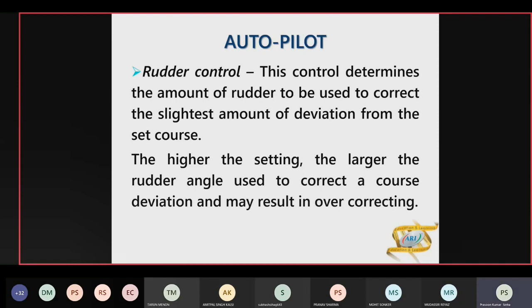To control the ship when she is going off heading, we were doing 320, it has gone to 323, 2-3 डिग्री shift हुआ. How much of rudder should be applied is set by the user. हम यहाँ set करेंगे 5 डिग्री.